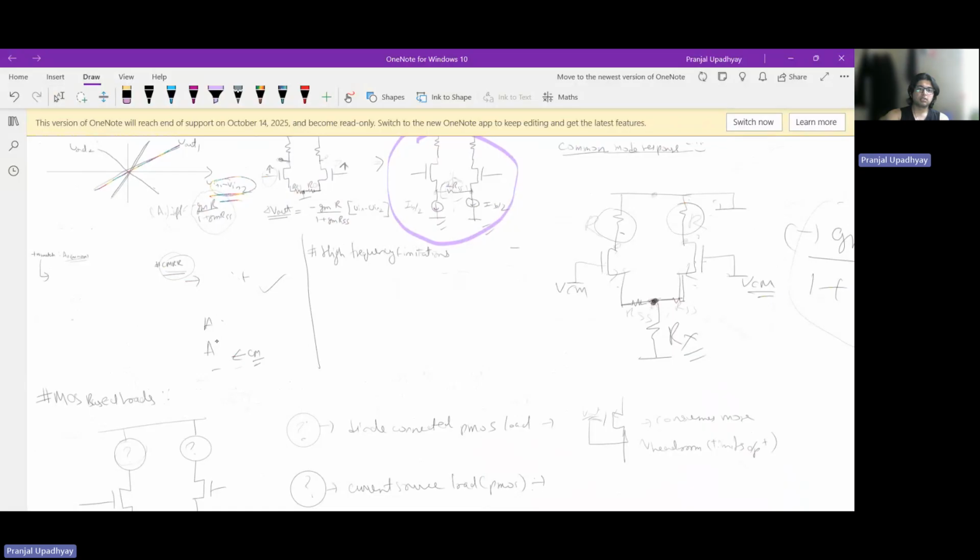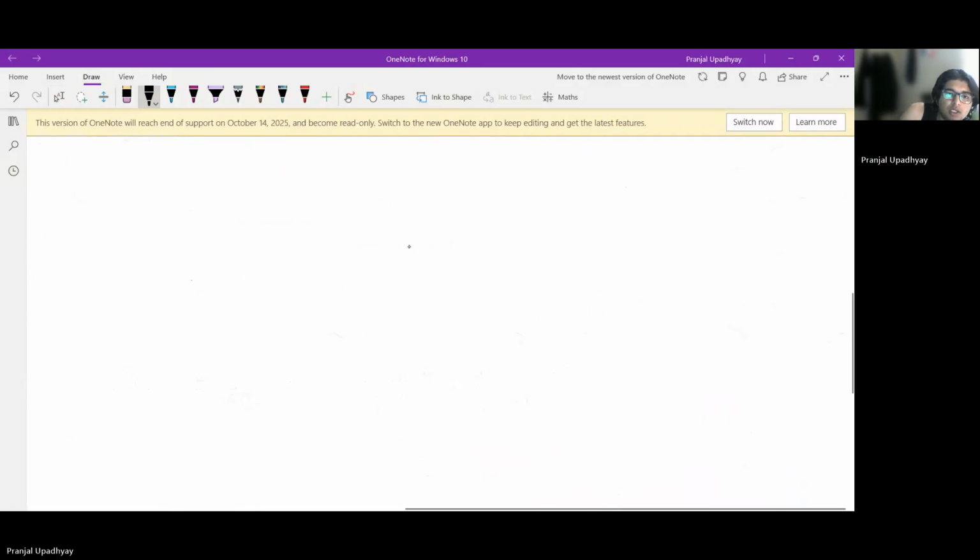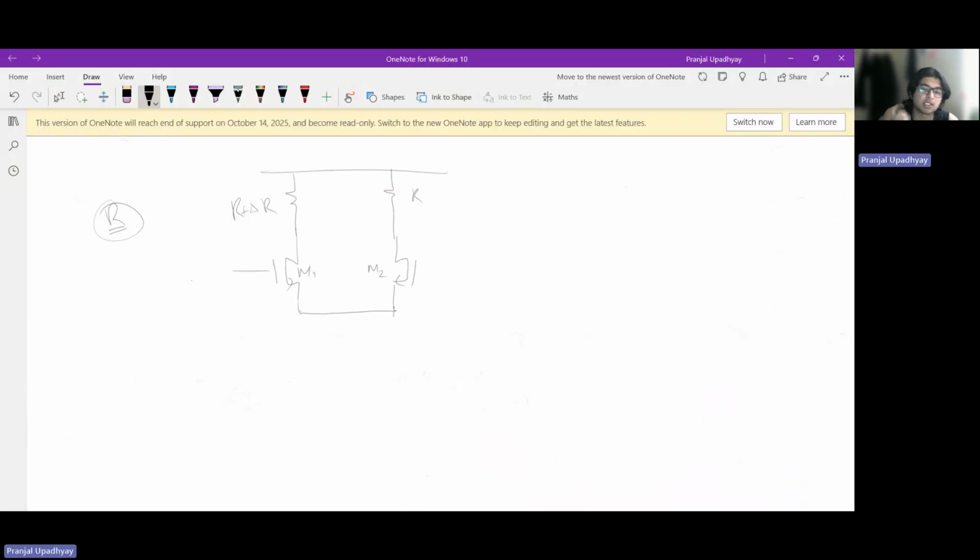And after we discuss the mismatch, we will discuss the differential amplifier with some active loads. Okay, so let's do this. Let us discuss mismatch, so let us discuss R mismatch. What we are saying here is that we have, let us define it as del R by R. Here we have R. Here I'm naming this guy M1, and here we are assuming that the tail current has some resistance Rx.